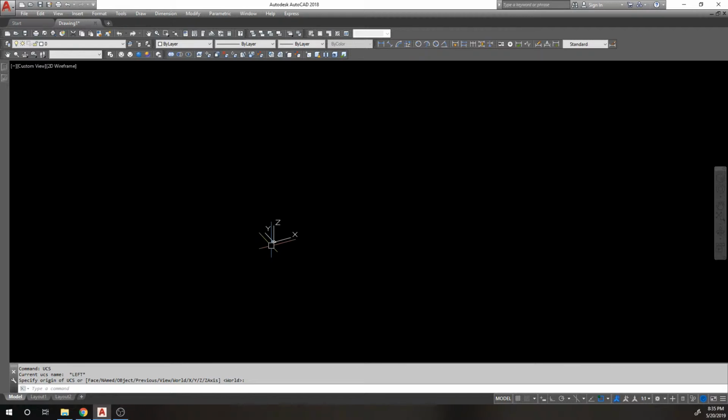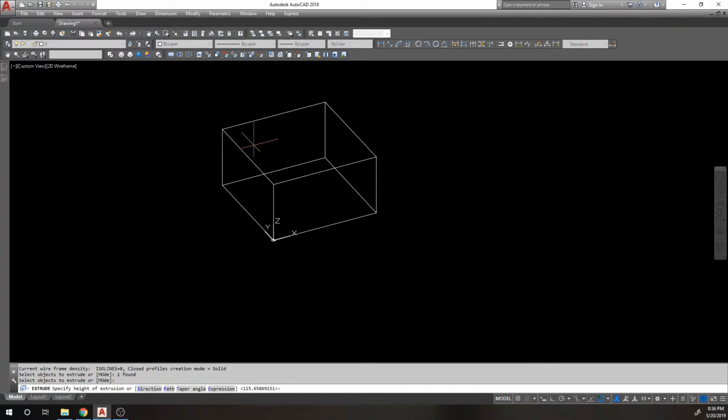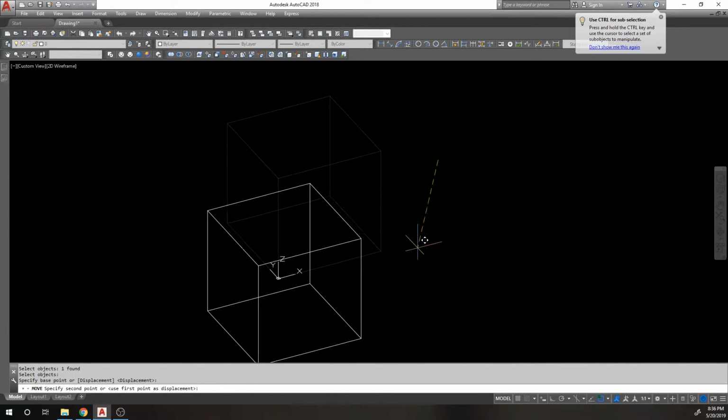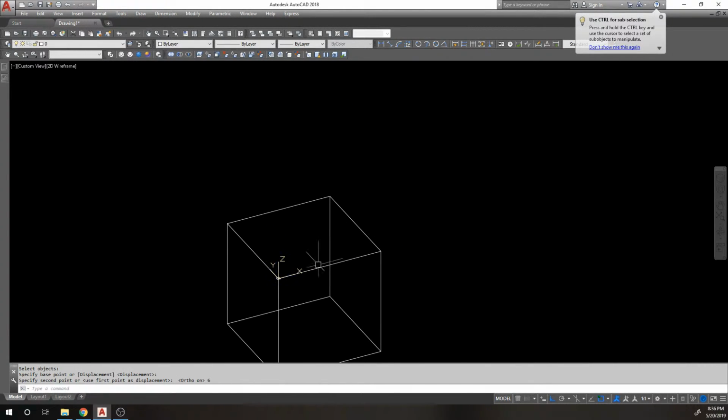This is easily discernible if I have like a cube. Let's say I come from 0, 0, 0, make a cube of 6 on 6, and I go there and up 6. You can see that this is looking down the top, even though it's set at the bottom. It's looking on the top, right? It's as if I were to do this. Turn the ortho back on, and there it is lined up with the top of this.